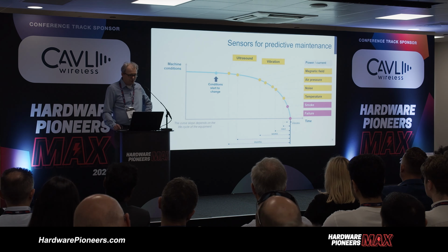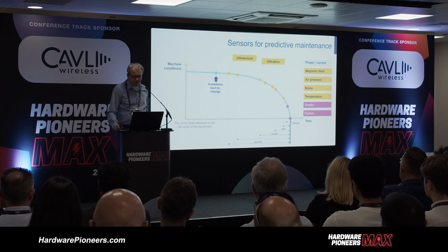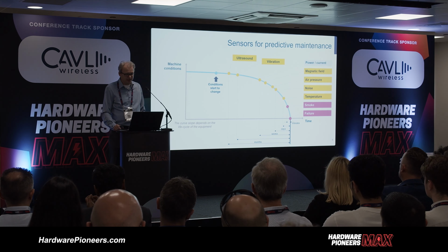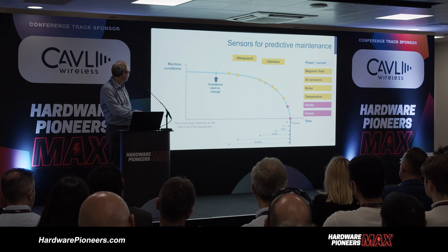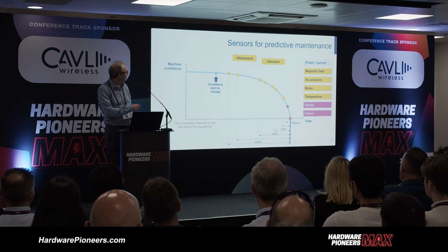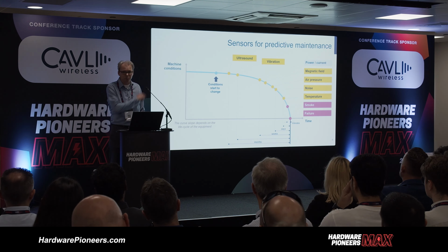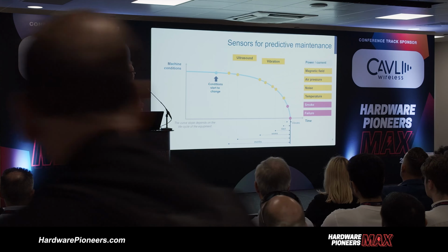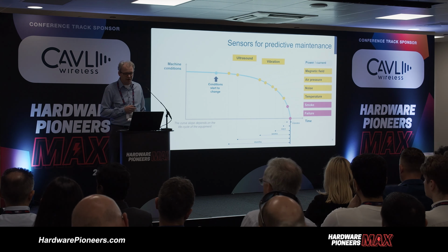And on this slide, I will show you some more concrete examples of what kind of sensors you could use. This is actually coming from different theory books of predictive maintenance. For example, for a motor, when the conditions start to change over time, one of the first artifacts that these start to generate is ultrasound, something that you could measure with a microphone, which we will come back to in the coming slides. The second artifact is vibration. This happens very early, the machines start to vibrate.